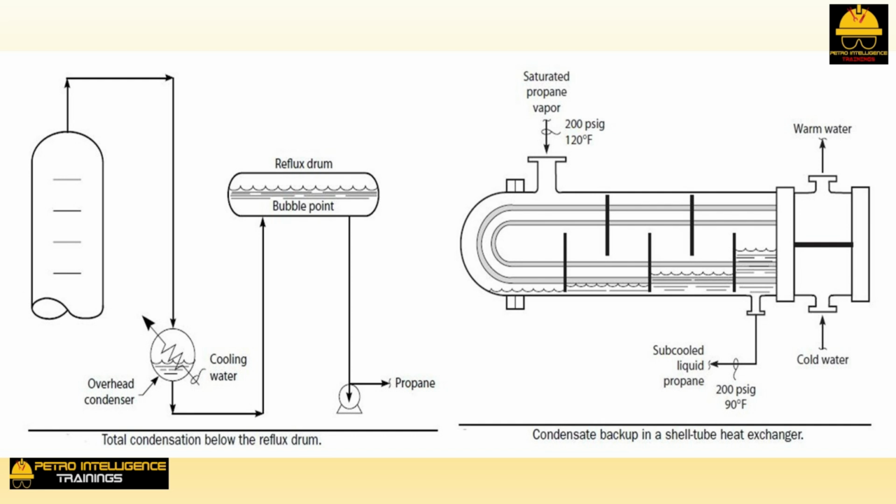The upper part of the shell will be hot. The lower part of the shell will be cold. The transition point corresponds to the liquid level of condensate in the shell. The condensate level will always be higher toward the shell outlet nozzle. Again, this all applies only to condensers in total condensing service.